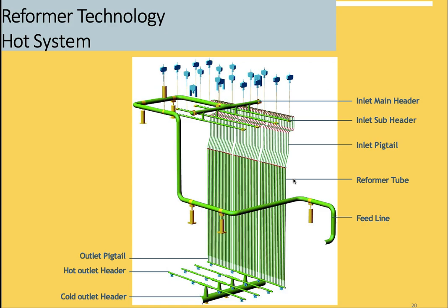I want to tell you that after we load the catalyst through the tube, we measure the delta P by a special device, not to face a problem like this in future. For each tube here, when you install the catalyst, you measure the delta P to be away from this problem. Use correct catalyst grading. Okay.